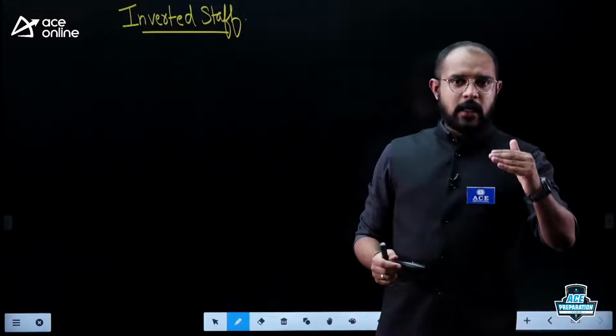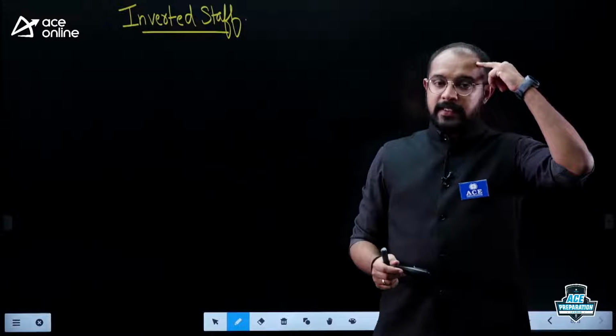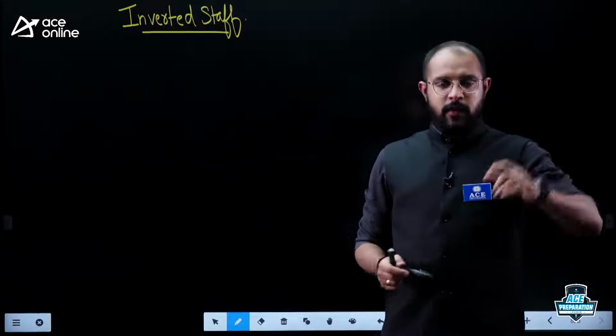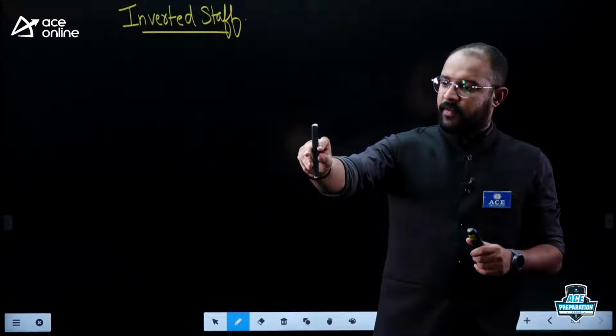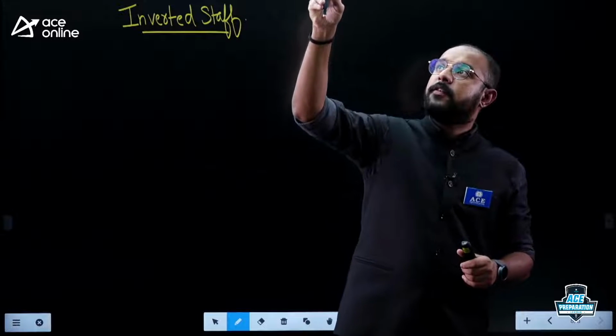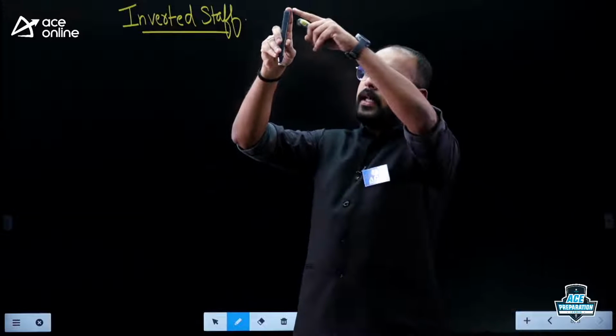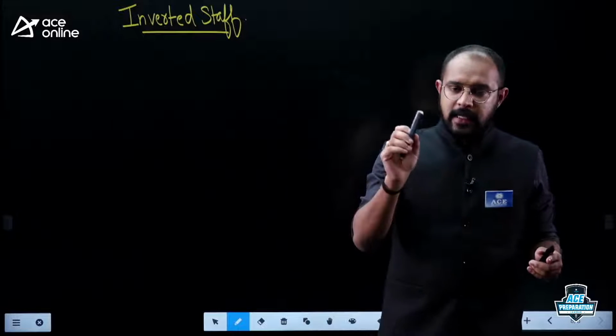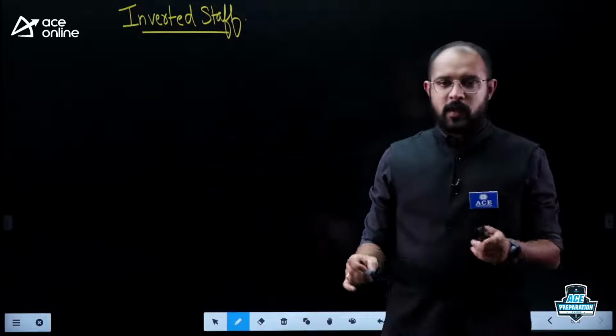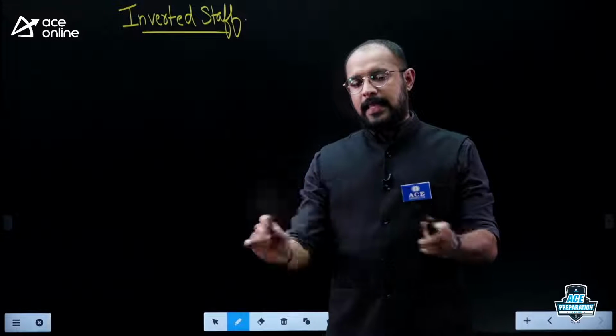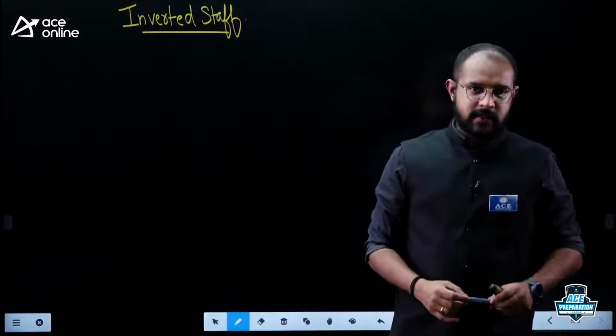Whenever it is required to find the elevation of a point lying above the line of sight, we call this point an overhead point. We take our leveling staff, hold it inverted, and touch the overhead point with the foot of the staff. This is the foot of the staff, and this is how my leveling staff looks. We call this an inverted staff. The reading against such a staff is what we call the inverted staff reading.